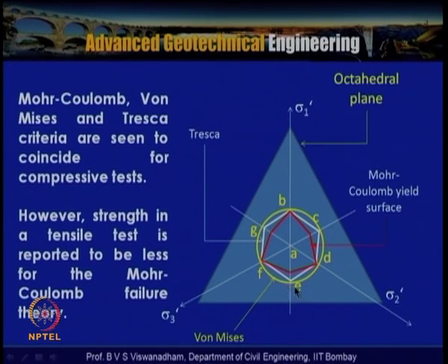The three yield surfaces are seen to coincide for the compressive test. However, the strength in the tensile test is reported to be less for the Mohr-Coulomb failure theory.